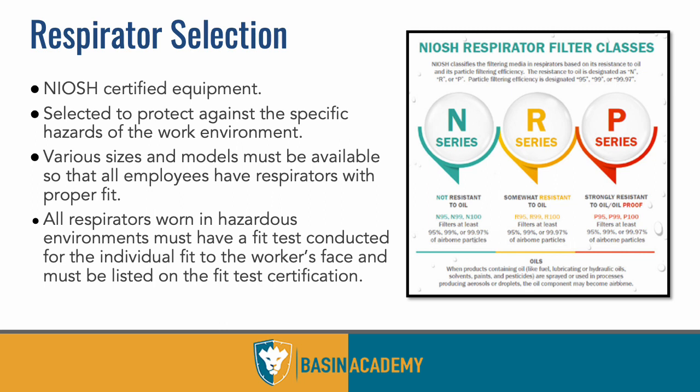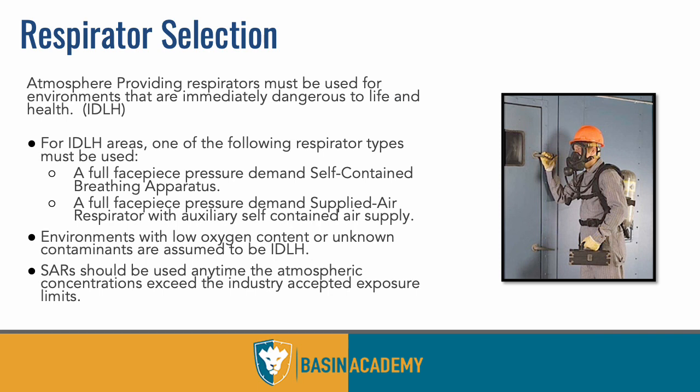Makes it easy in oil and gas, specifically H₂S. Scott, MSA, and 3M, as well as Draeger and a few others, have kind of the standard package that's good for oil and gas, is resistant to grease and oil, and will protect you from H₂S, which is the full face piece breathing apparatus. So for ideal H₂S atmospheres, again, we need to have that full face piece pressure demand self-contained breathing apparatus, which is the full scope of it.